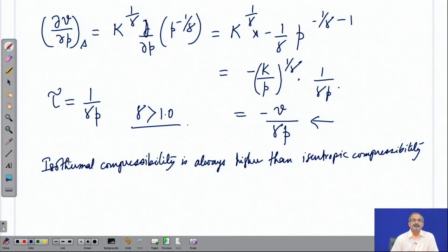Okay. So, whether isothermal or isentropic, if the pressures are considerable, then there will be significant changes in density, and therefore, what finally matters is the density change. A few percent change, typically restricted to about 1 or 2%, may be ignored, and then we can consider that kind of a situation as incompressible.